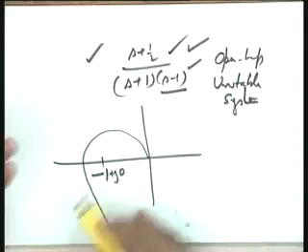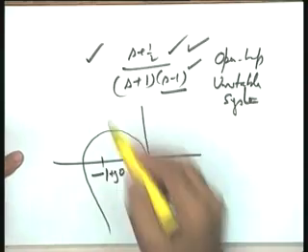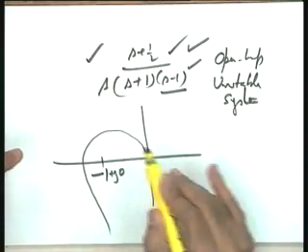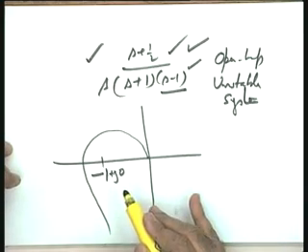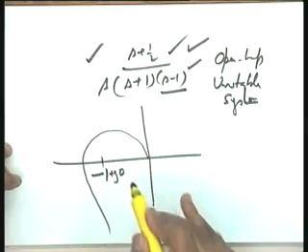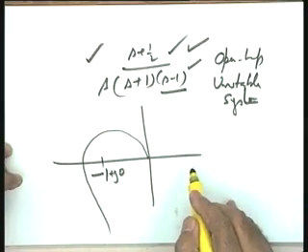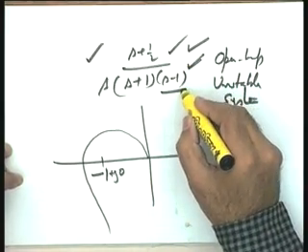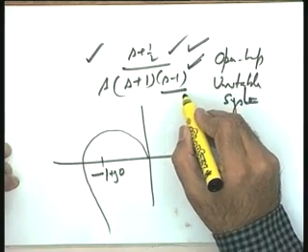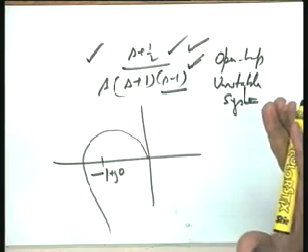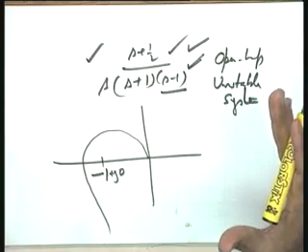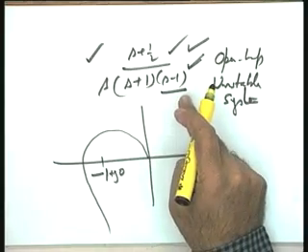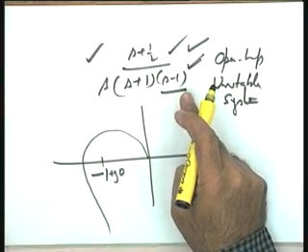Let us assume, though in this particular case it will not be a plot for this, let me put some s also, because then it may take this shape. Let me assume that it is this shape. In that case, the system will be stable only if there is one encirclement in the counterclockwise direction, and that encirclement corresponds to the open loop pole in the right half plane. It is not that the definitions of gain margin and phase margin cannot be extended to situations where the open loop system is unstable, but normally we do not do it.